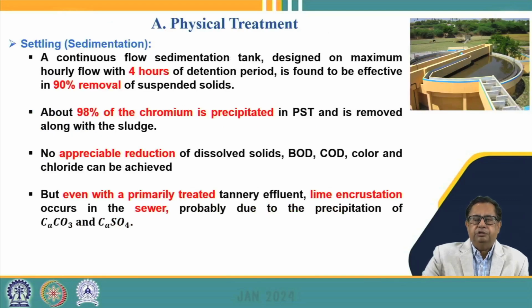After the screening process, we may go for the sedimentation or settling process, where we try to remove the particles which were not removed by the screens and have come into the settling tank. It has been seen that if we provide a detention period of nearly 4 hours, it is very effective in removal of suspended solids, and nearly 90% of the solids can be removed by a sedimentation tank having a detention time of 4 hours.